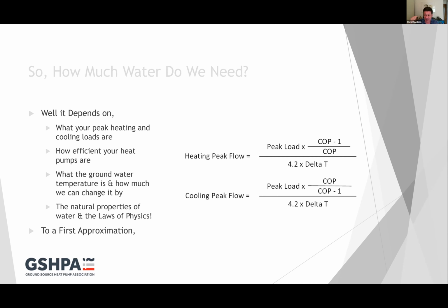Whereas in London, you might get away with more, but you've got to consider the fact that the Environment Agency and GSHPA consider heat to be a pollutant, and so they will have a view on what delta Ts you can use on any given system in both heating and cooling. Typically 10-degree delta Ts are accepted, but it is part of the process with the Environment Agency.